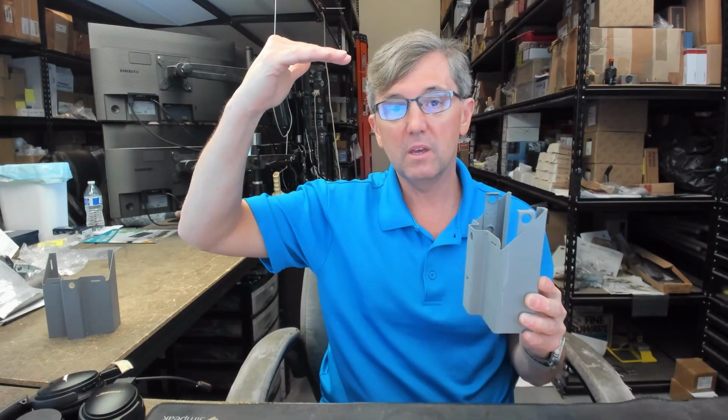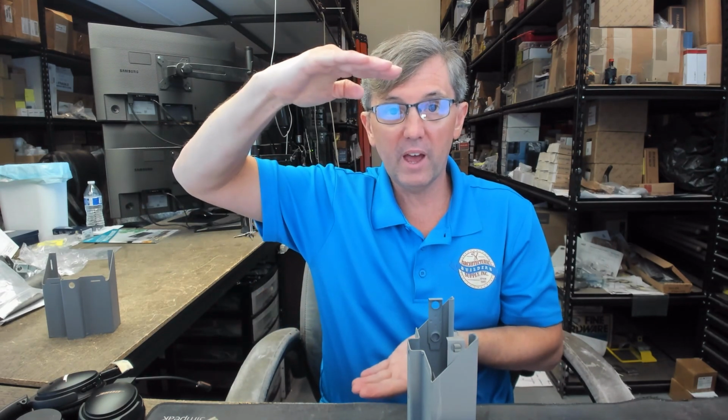Inherent in a drywall frame is needing to know the rough opening size. In that same 3070, if you've got a 2-inch face and a 2-inch face, the OD is 40 by 86. Your rough opening, stud to stud, floor or whatever the sill is, to the underside of the rough header is going to be 84 3/4. You've got an 86-inch overall height. So a relationship between the door size and the distance between the studs and the floor and the header is also inherent in a drywall frame.